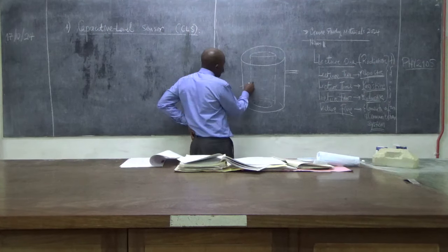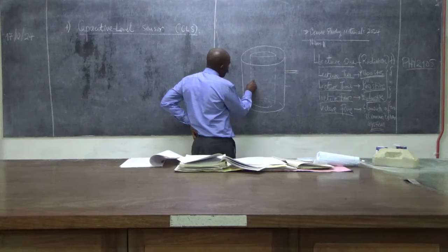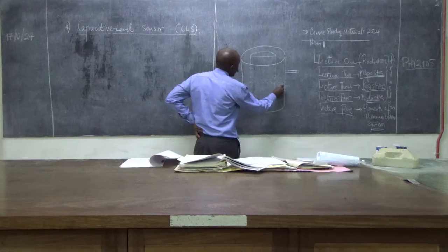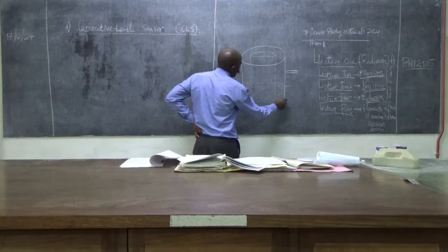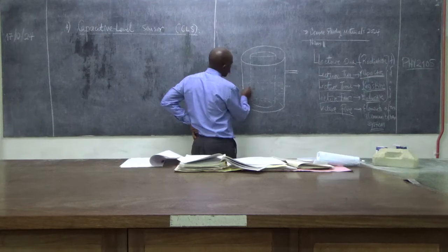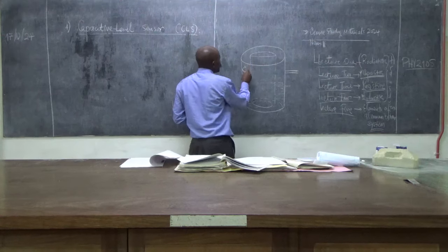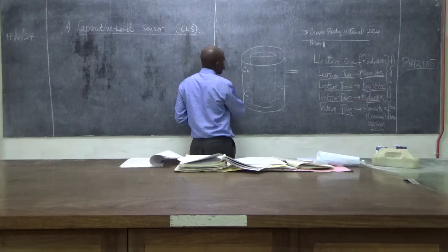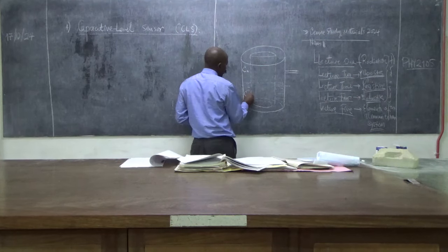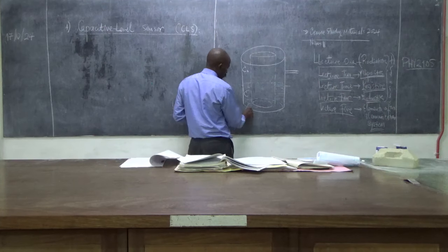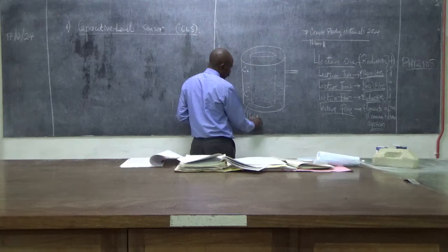So this is the fuel, the liquid level in this part of the capacitor, this side here. Then you will be having capacitance here and another capacitance, so this is capacitance without and capacitance with the dielectric. Now which dielectric is there? Fluid or liquid.